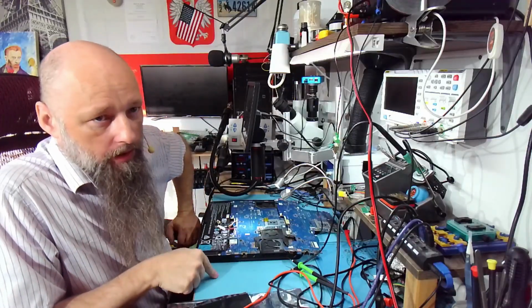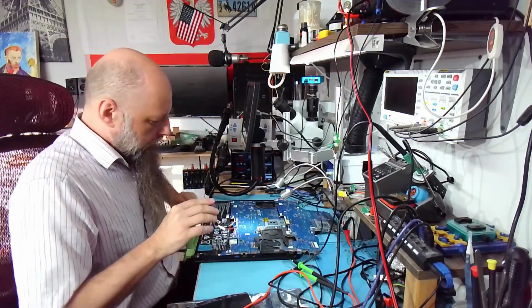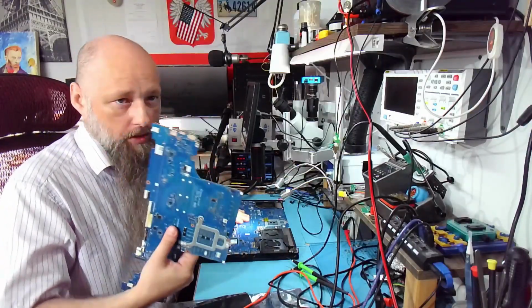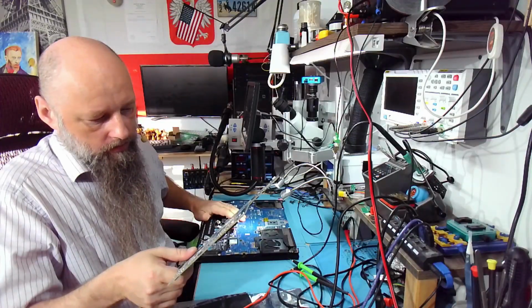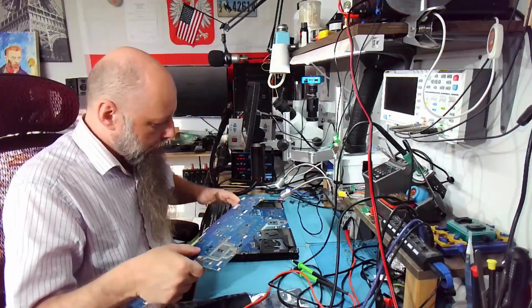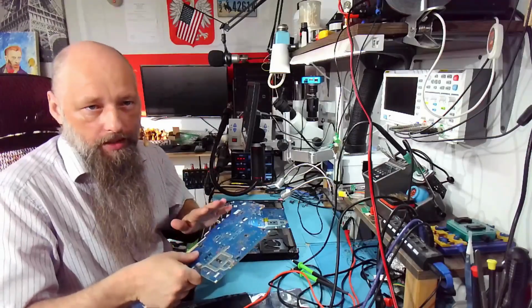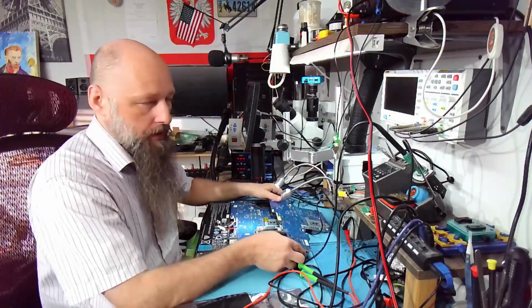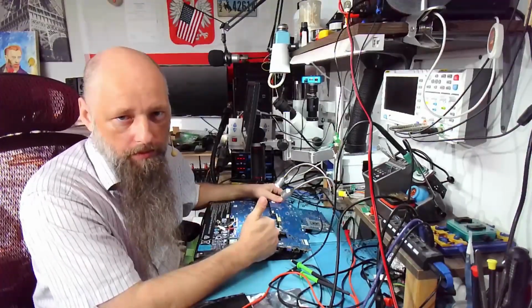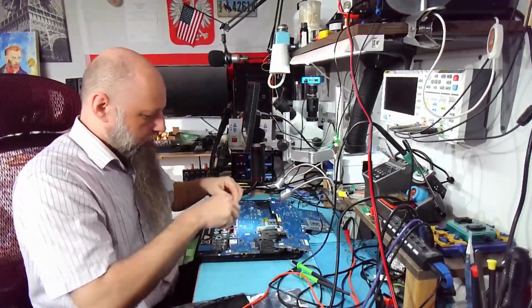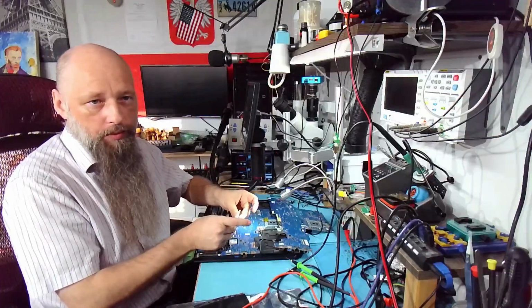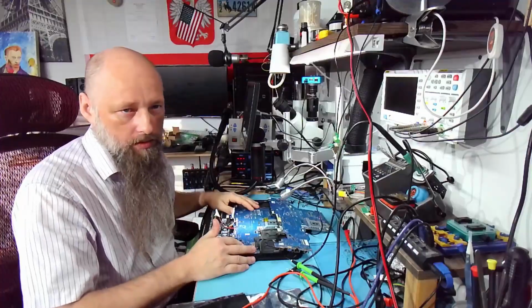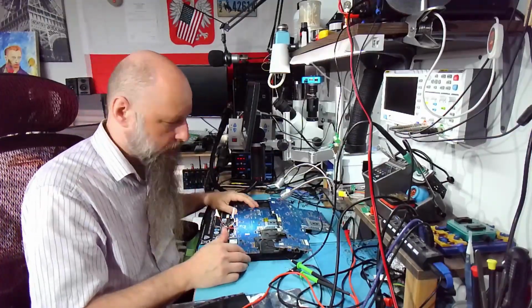But number one, why does it not charge? This board is not the same board as the original. And the main issue with that is that they might have different programming in both the BIOS and EC. Which means the battery might just not be compatible with this one, right? Because the battery, we have two cables over here. We recharge the battery manually so I can install updates, because you can't install updates if the battery is not at like 40% or something.